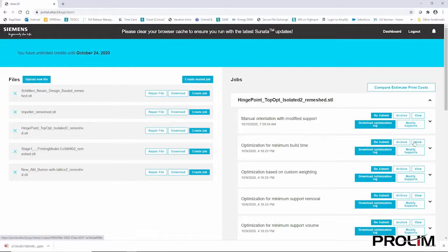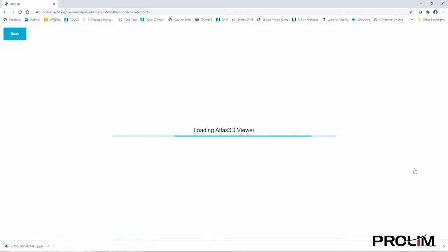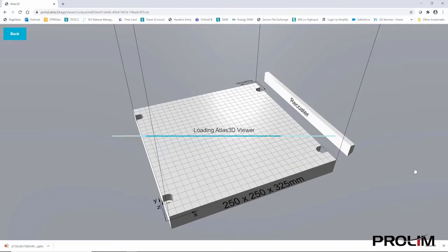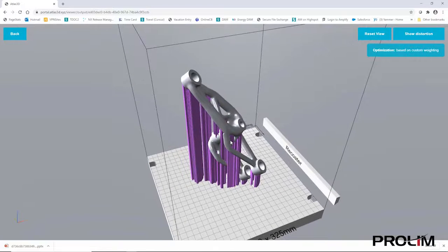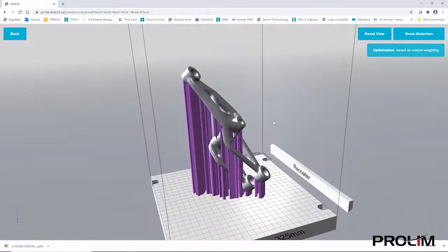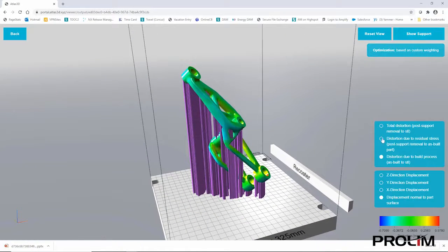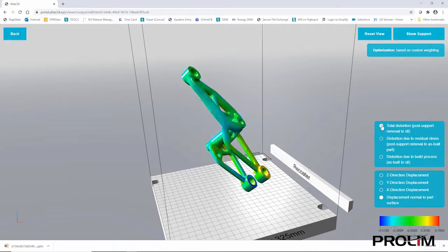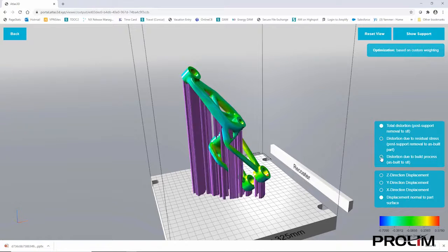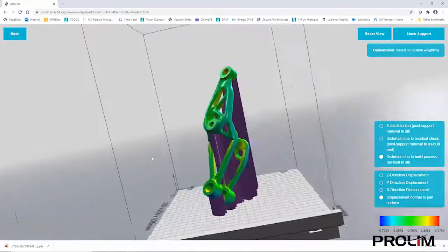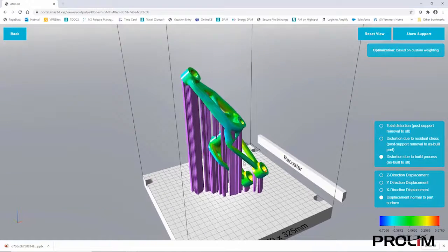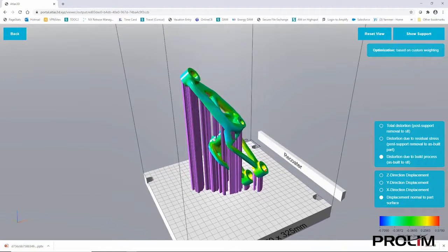Now, once you have the part you want to print, it makes sense to optimize the printing of that part, not as in topology optimization, but as in optimizing the actual production. So for example, Siemens has software for optimizing the orientation of the part in the build tray. This helps minimize distortion, minimize material usage, etc., so that your production is optimal and your part will print with quality the first time. Now, this particular system, called the AM Build Optimizer, is cloud-based and uses parallel processing running over 100 different orientations in parallel to find the optimal orientation for your part in the build according to some weighted inputs that you give the system.